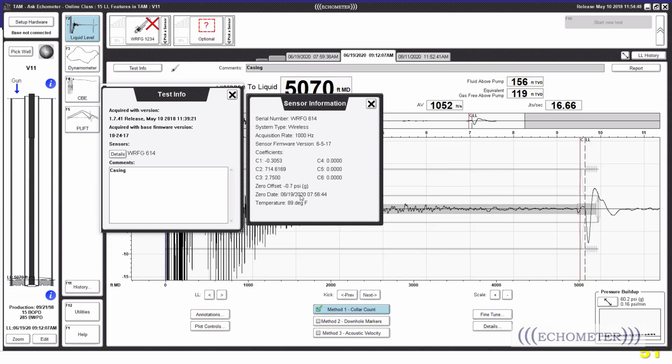Lots of times if you are zeroing your pressure transducer at different times during the day, it's different temperatures outside. And so the temperature does have an effect, and we've seen zero offsets. If your zero offset is +1 or 2 or -10, as long as it's within a reasonable range, you want to look from the last time you checked that zero offset to this date, and keep comparing those. You're looking for a big change in the zero offset. You're looking for a possible drift.